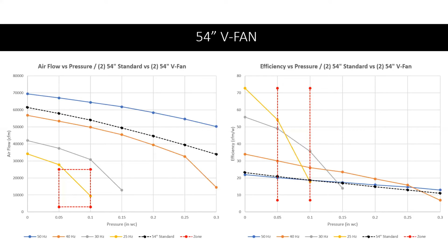And then if you go over to the right-hand side, you can see that yellow line is up almost at 55 CFM per watt, just really high performing. But there again, the yellow line does drop off fairly rapidly, but the gray line does not. So being aware of what static pressure you're actually running in min vent rate might dictate how low a speed you go.